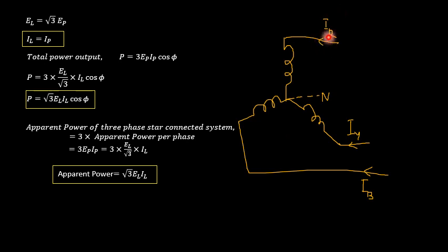So in this, if you see, IR current is entering. This is the individual line R, line Y and line B. So we have the current IR, which is called a line current. If you see this particular phase, the current which is going to flow from this particular line is going to enter into this particular R phase. Similarly, it is having another connection given to the neutral point. So it is just behaving like your series combination, which states that the current will remain the same.